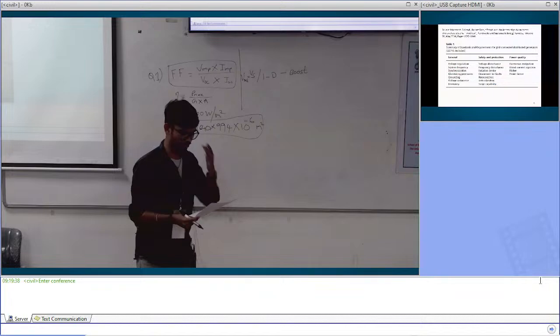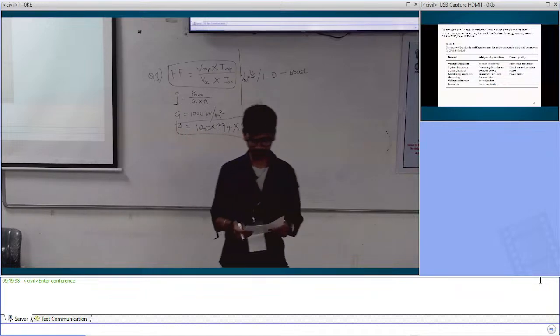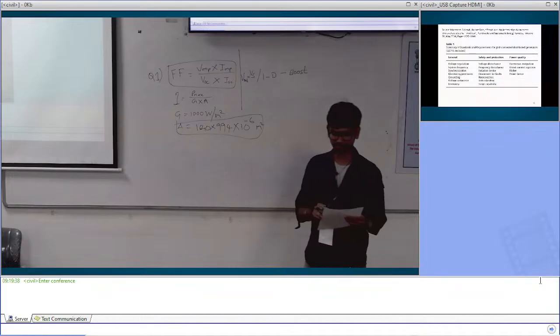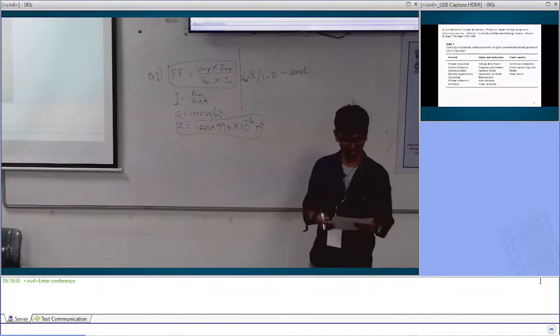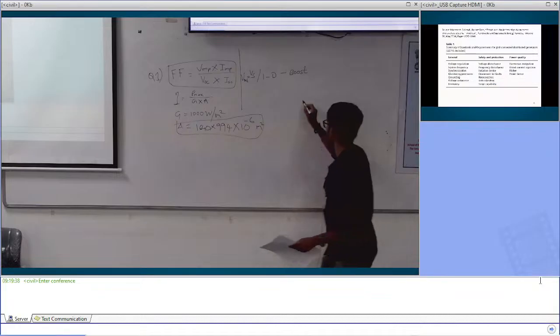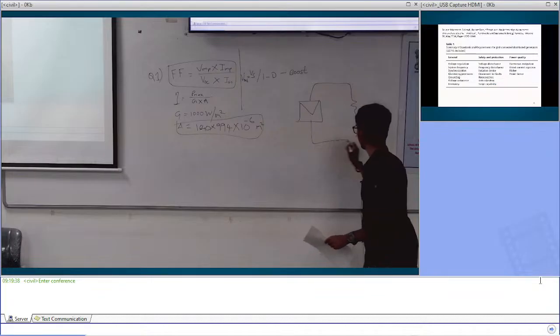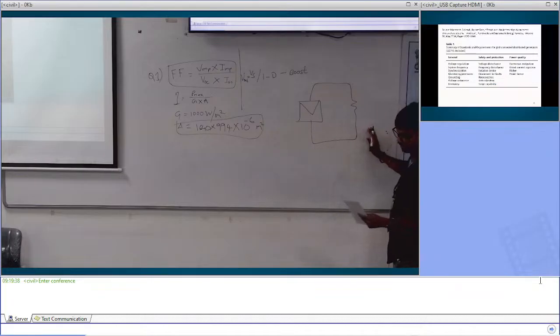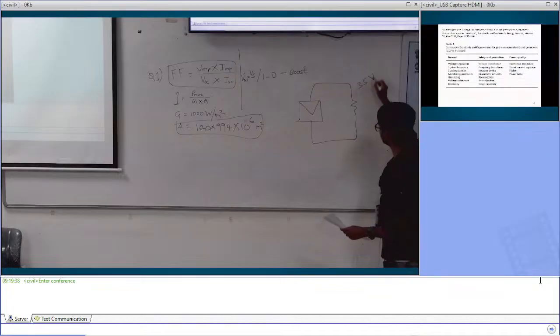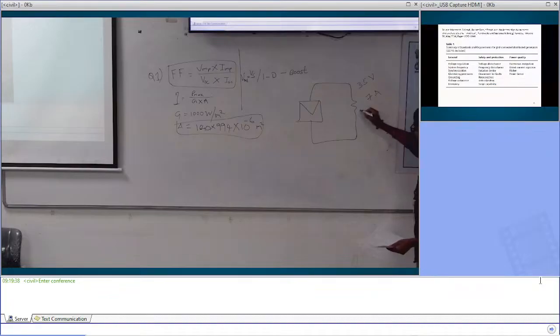The next part of the question, we have calculated the operating point with 35 as voltage and 7 as current in the normal condition, that is, PV is directly connected to a resistive load. At this condition, we have operating point as 35 volts and 7 amps of current. With this we can find the value of R. V equal to IR, so we can find the value of R. Now we are telling that now a boost converter is connected in between panel and the same resistor.